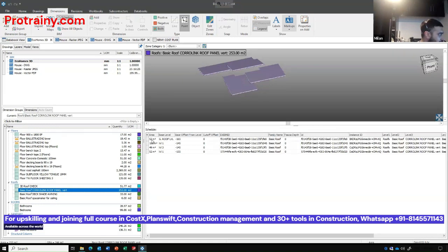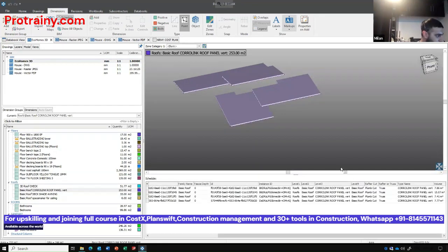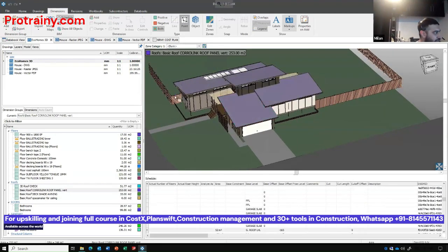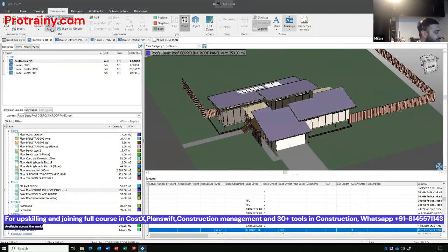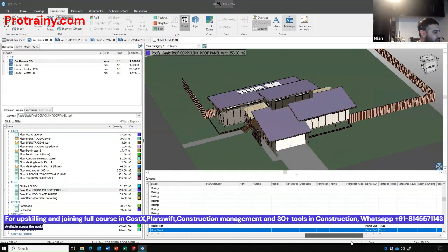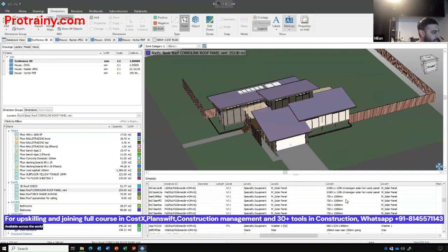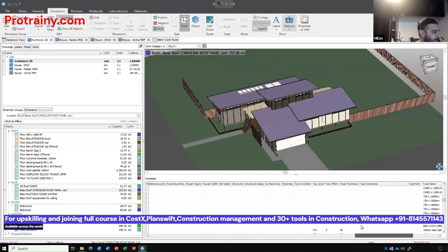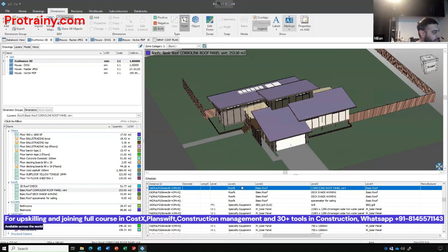Here we can see the area. This is the schedule where we can just note all of the properties that are coming from the model. Let's show all objects. There are much deeper quantification tools like model maps, which we won't go into today, but they allow you to use the information in the schedule to your requirement. So if you need to structure this by specialty equipment, by different sizes, it's possible. You can also export this schedule out and import your own information.